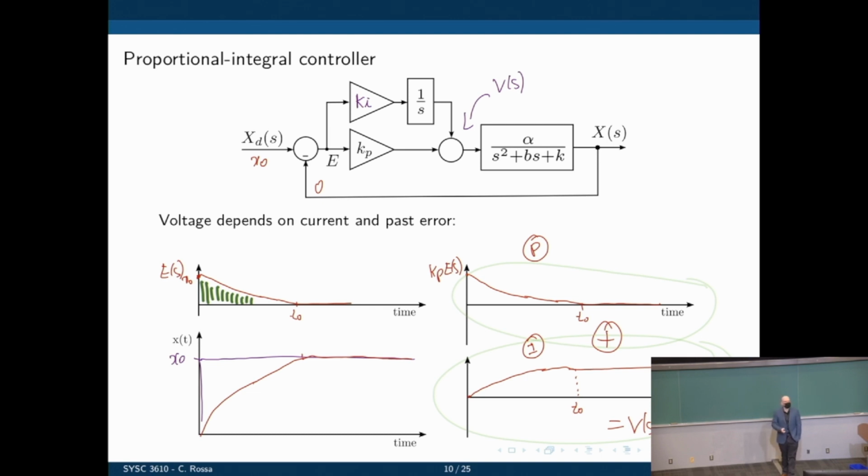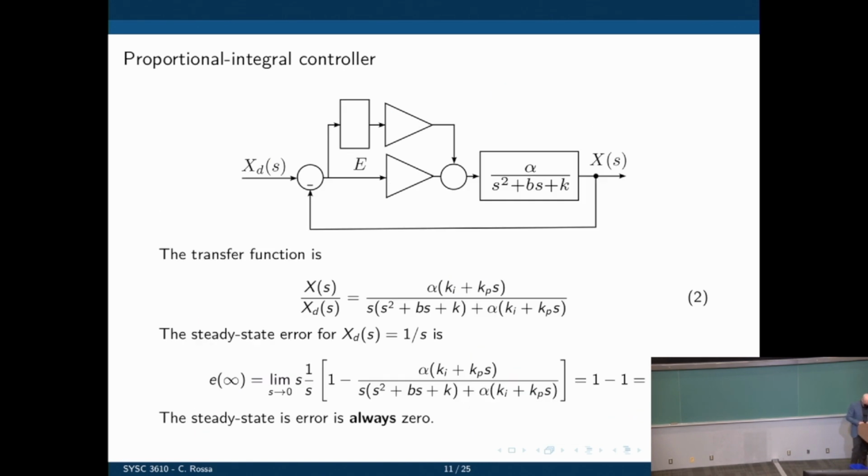What is the result of that? Overshoot. The system will accelerate too much, potentially, and it will exceed the maximum position before it goes back. So the problem we created here is we eliminated the steady state error, but now we are introducing overshoot potentially. Because especially in the beginning there's a lot more energy delivered to the system to make it move. So it will accelerate faster, and it will likely exceed, because of inertia, x0 and oscillate around it before it settles. That's where the derivative gain comes in. It will help with that.